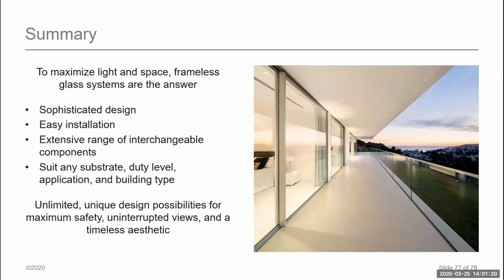Typically, base shoes are going to be the major component element that we'll see with that. Again, they're very simple in nature. They're very modular in nature. They're very easy to install. We did not talk about post and rail systems, but as I said, we reviewed this. We have the base shoe. We have the glass. We have basically the gaskets that hold it and the wedges or the Q-disc that holds in the glass. And then we have a cap rail, very simple in nature.